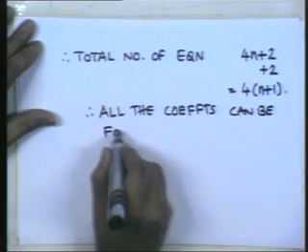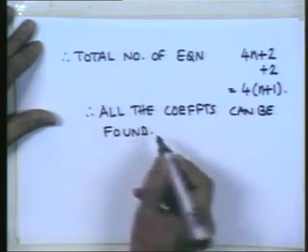All the coefficients can be found, and given any set of initial and final positions, velocities, and any number of via points, without the user having to tell you what the velocity is, based on the simple heuristic that smoothness of motion demands the velocity and acceleration be continuous at all the intermediate via points, you will be able to fit the entire trajectory from the initial position to the final position, making use of the cubic curves.